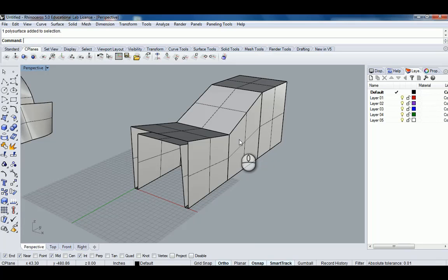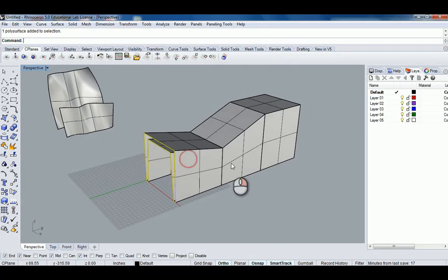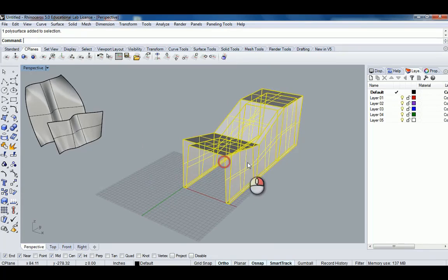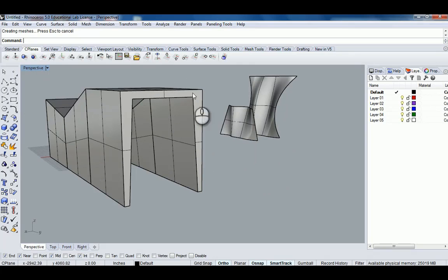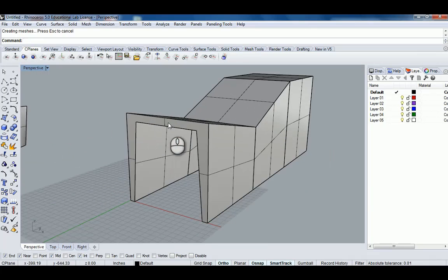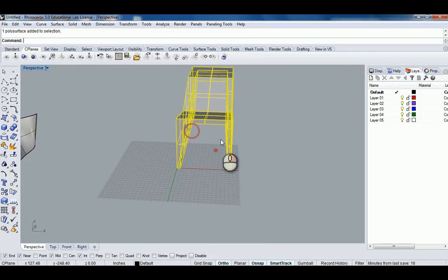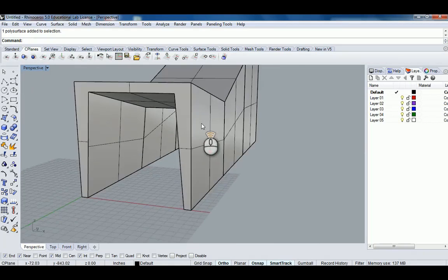Yeah. So if there's a closed shape and we do use straight sections, we could go back and simplify the surface, but it will create a poly surface that tries to cover all of those points inside and outside. We could cap this thing because it has clean edges, right? Like we looked at before, those naked openings on each side were coplanar. So the cap command will close that just fine. So this shape, for example, we could 3D print if we wanted to. It's watertight. This could be printed.